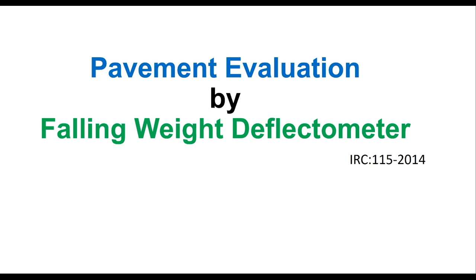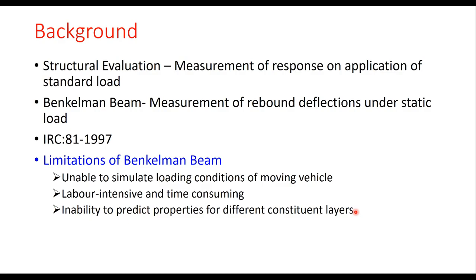Today I will discuss a very important, new topic: pavement evaluation by falling weight deflectometer. This procedure is covered in IRC code 115/2014. Structural evaluation is based on measurement of response on application of standard load.